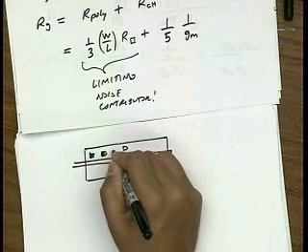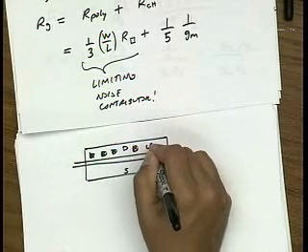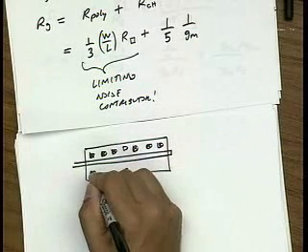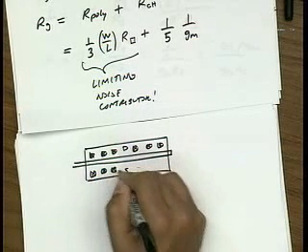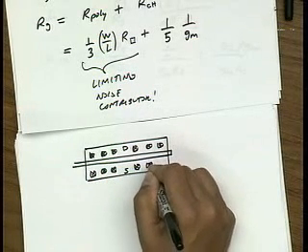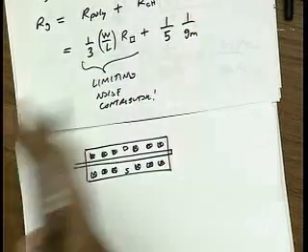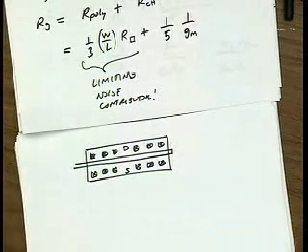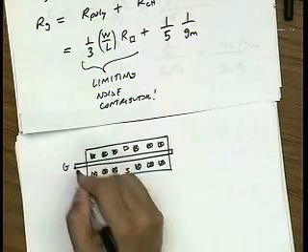So these are my contacts on my drain side and my source side. Right away you could say, you neglected the noise of the drain resistance and the source resistance, and that's true. That'd be another good question I can ask you on the midterm: calculate the noise of a common source amplifier, but include the noise of the drain and source region. Okay? So here's the gate.